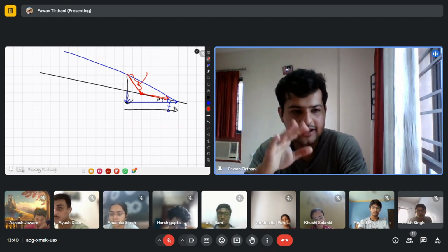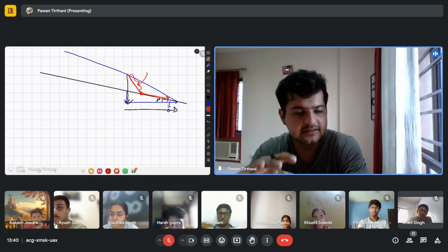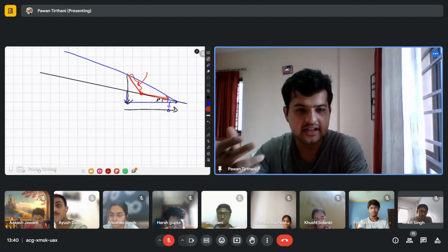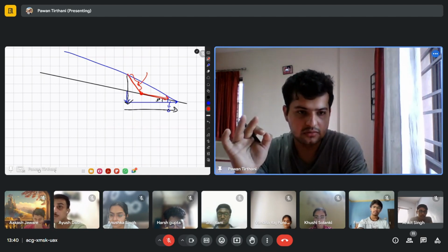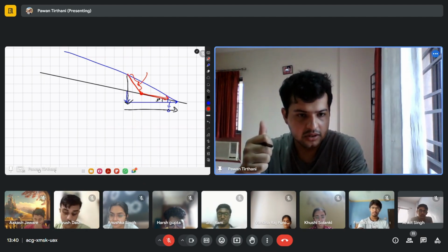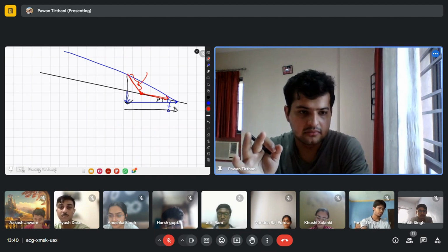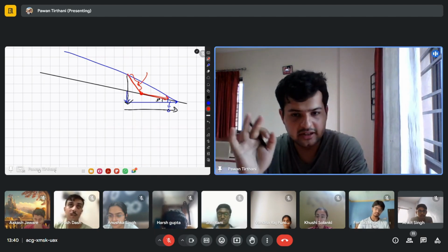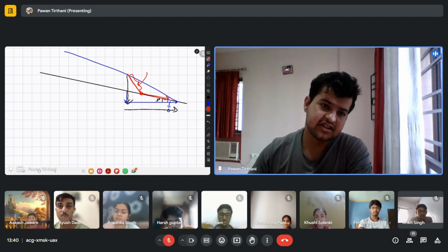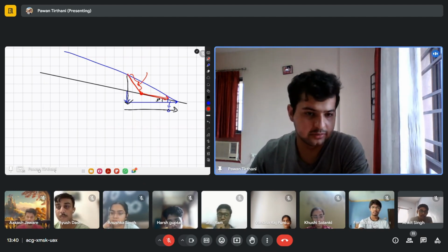So landing के time पे major problem होता है unstable approach. If you have an unstable approach, if your speed is too high, if your altitude is too high, if there is too much turbulence, you cannot control the aircraft, go around. Okay? कोई आपसे कुछ भी नहीं पूछ सकता. If a pilot has gone around, that means everyone knows that going around was the safest course of action. You can always make another approach.